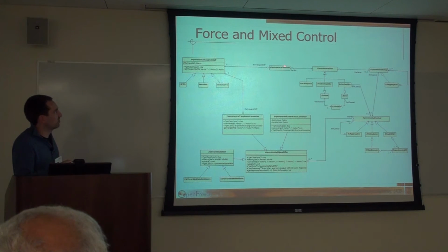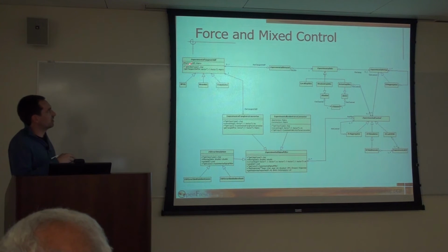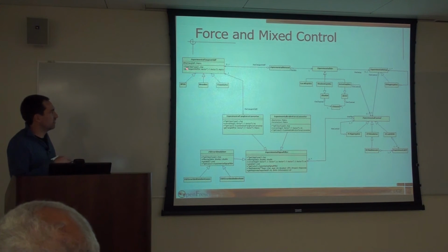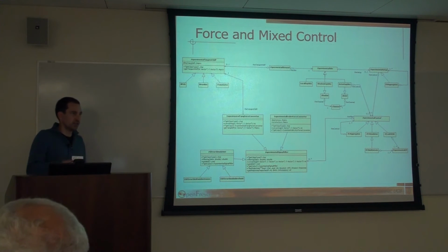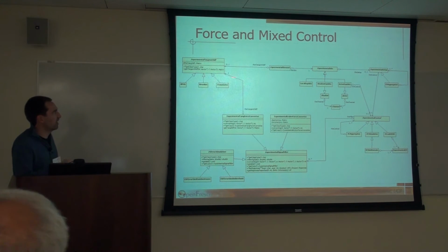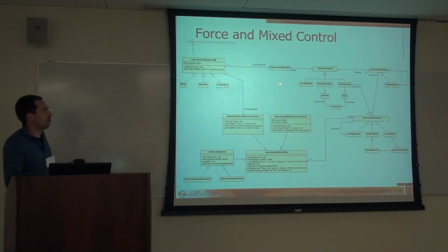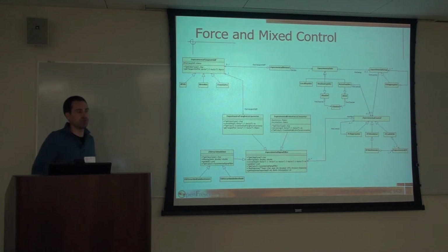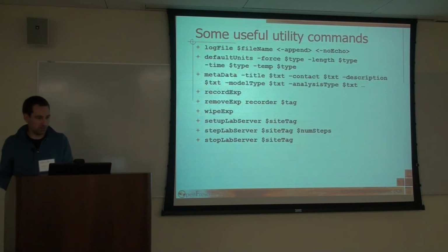For your experimental element, we have an experimental tangent stiffness class. This class has different subclasses, like EBFGS, Broyden, and transformation solve, and so on, that can calculate the tangent stiffness on the fly. By connecting this new class with our experimental element, we now have the choice: do we use the initial stiffness matrix, as we've been doing for many years, or do we try to calculate a tangent stiffness on the fly and make use of that?